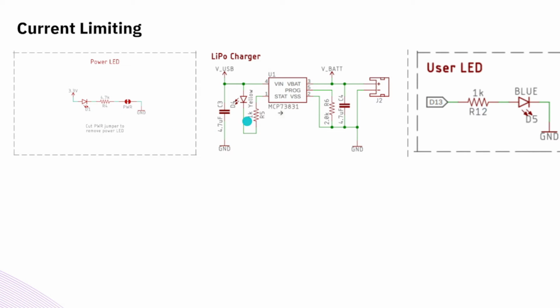And the reason for using this resistor is for limiting the current flowing through this LED. Now let's talk about how these resistors are getting selected. If you have to design something like this, and let's say I replace this yellow LED with a red LED, will my resistor value change? Obviously yes.